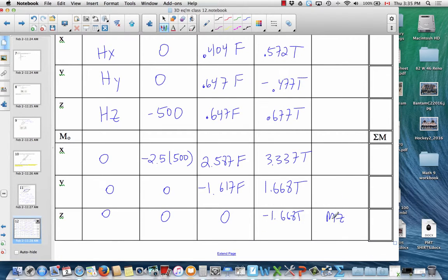Now, a Y moment is not needed. So you make minimal assumptions in order to get a solution. So this Y moment is not needed for a consistent solution. So we assume it's zero. And we said earlier the hinge cannot resist an X reaction moment. Sorry, it cannot resist an X rotation, so there cannot be an X reaction moment. All right, so now we proceed to solve these equations.